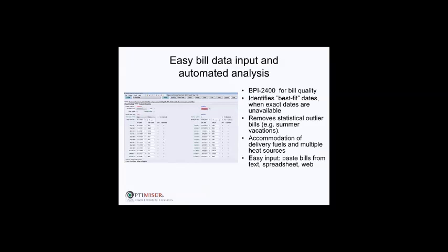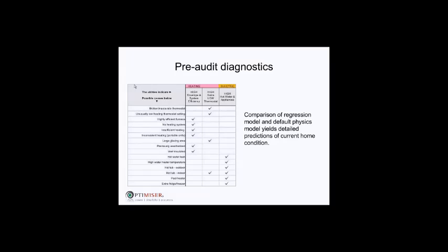And so then it gobbles that up and it compares it to weather from the same time period, and it gives you some results and tells you how the analysis went, and then it automatically applies the information as best it can in the most appropriate way. So if you don't have enough information, say you have 2 propane top-offs or something that you've put in to the model, we might not be able to disaggregate heating, cooling, and baseload from that, but we can calibrate towards it.